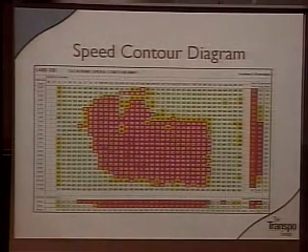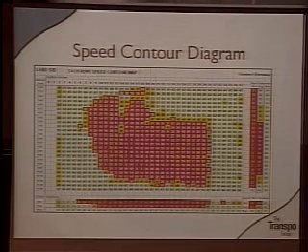When we have access to floating car studies information, what we like to do is to display the information on this type of time-space diagrams that actually show the speed at given sections along the freeway, average speeds on 15-minute time intervals.